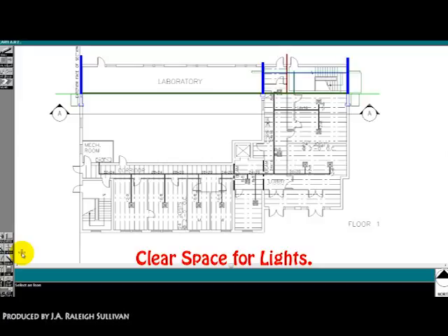This is really tricky. Usually the section cut is not cut at this location. The tendency is to simply draw what is at the section cut line without regard for the rest of the building.